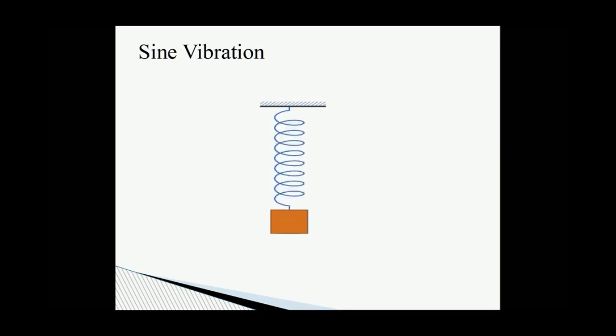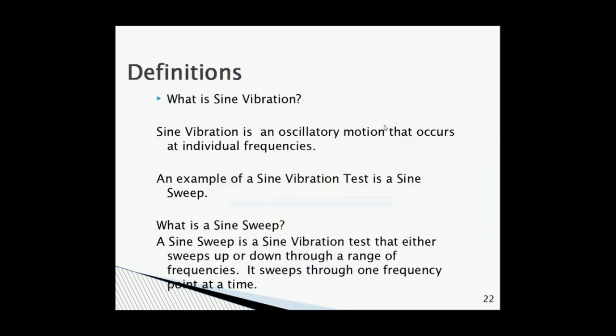Okay, well, you have 10 cycles. I have 10 seconds. Let's go ahead and divide 10 cycles by 10 seconds, which gives you a resonant or natural frequency of 1 hertz. So this spring mass system is moving at its natural frequency of 1 hertz, which also explains why there's so much displacement, because at lower frequencies you have higher displacement. Okay, let's go ahead and move on.